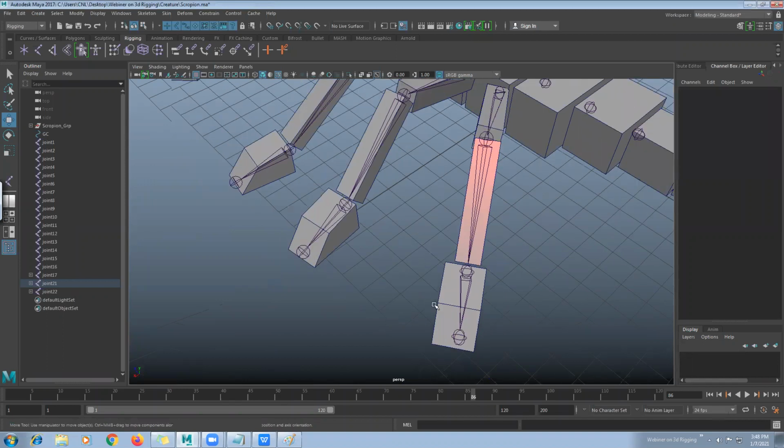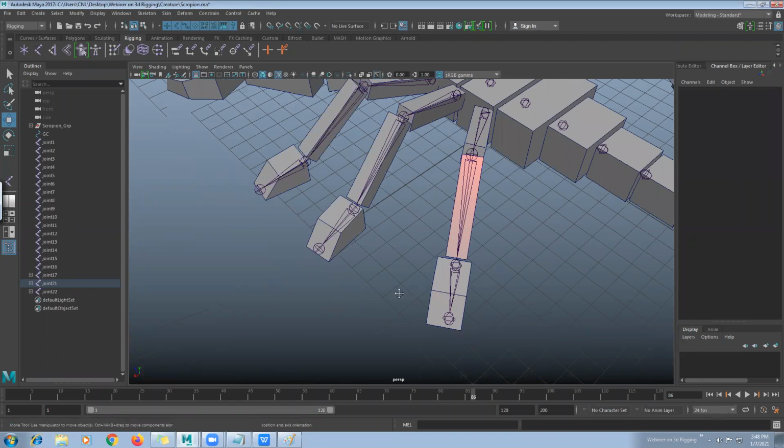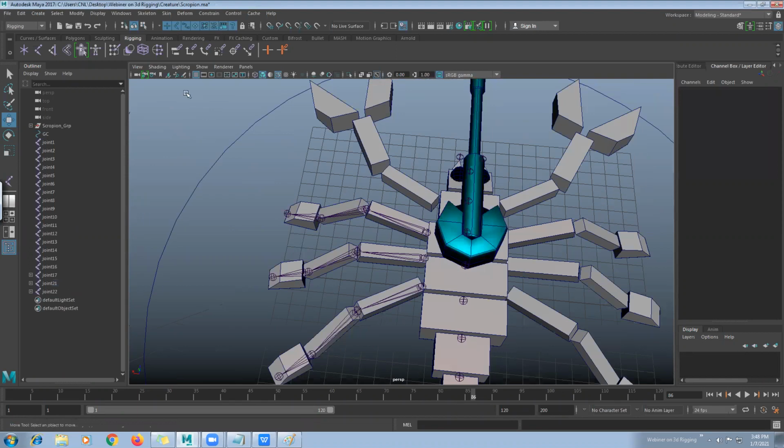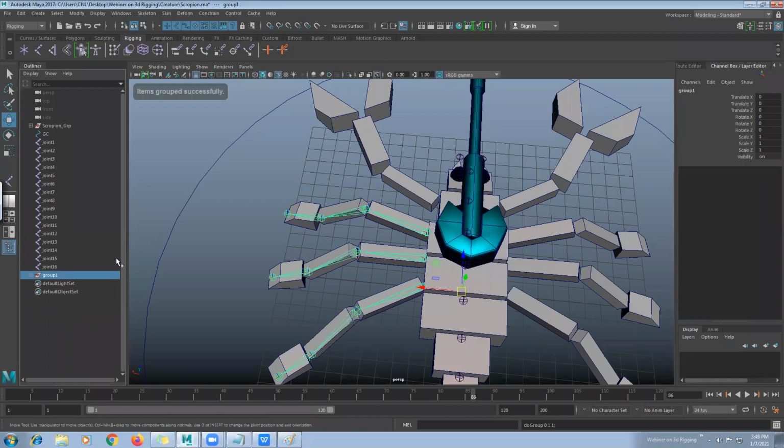So this portion, which is called the left side, we already completed. Now we should jump to the right side. Because it's a symmetrical object, it's very easy to do. Copy all of those together like this and hit Control G. That creates one group exactly in the center.